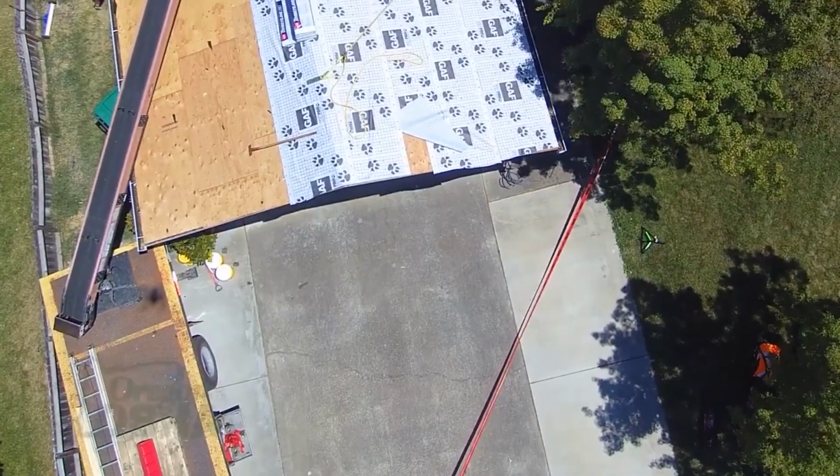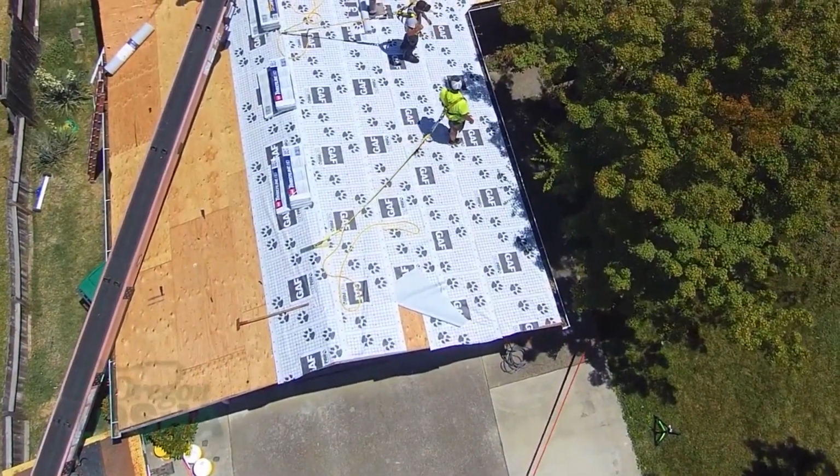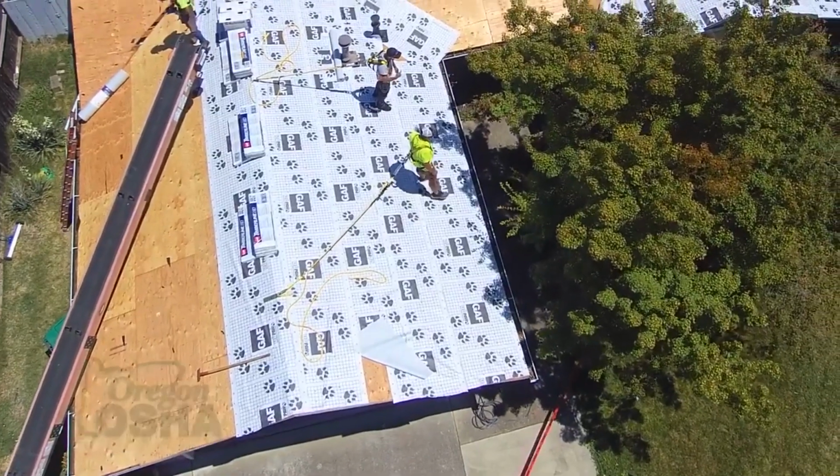In that pre-task safety plan included typically is the fall protection methods that we're going to be using. They also review extension cords, power tools, anything that gets plugged in, having a weekly check of those. And so the pre-task plan can include as much as even parking, where you're going to park your vehicles. Pre-task plans typically include your HAZCOM, your data sheets for the materials that you're going to have on the roof, where that folder is going to be located, or where that information is going to be located. So that is all part of that pre-task safety plan.